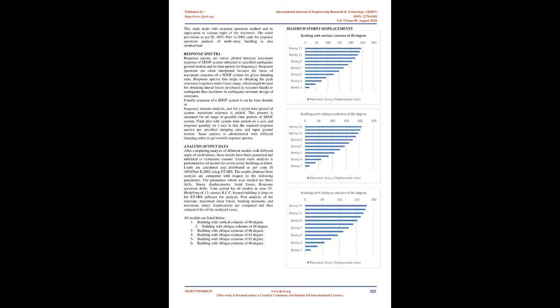Response spectrum analysis. The response spectrum method stems from the modal method or mode superposition method. It is best suited for the kind of structure where a single fundamental mode importantly influences the response of the building. Basically this method is used for the dynamic analysis of buildings. It is broadly used for areas of discontinuity or irregularity, i.e. asymmetrical. It is available for the analysis of forces and deformations within multi-story buildings under average intensity ground shaking, which is said to be moderately huge but linear in response within the buildings. In its form, this method for linear response is suitable to arbitrary 3D structures.